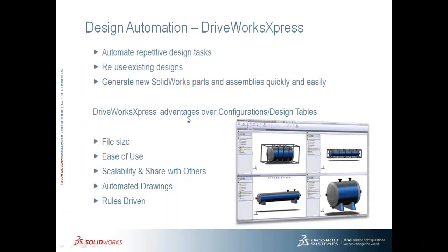So as we have seen, DriveWorks Express is used to automate repetitive design tasks, reuse the existing designs, and generate new SolidWorks parts and assemblies very quickly and easily. I mean, configurations also do the same, but in DriveWorks, you can save the file size because you're not creating the configurations inside the same part, and it's very easy to use once you create the database, and you can share it with other people.